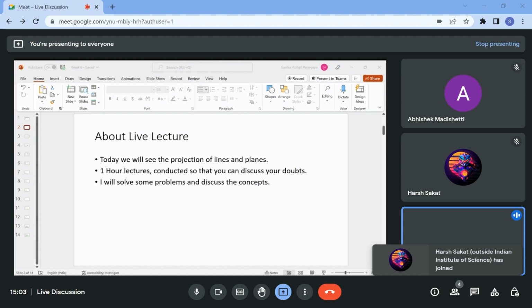But in this case, if I want to see the angle with respect to VP, I need this line to be parallel to the horizontal plane. But when I started, I had already tilted it 30 degrees with respect to HP and then tilted it with respect to VP. So whatever angle I see here in this figure is not the true angle with respect to the vertical plane.